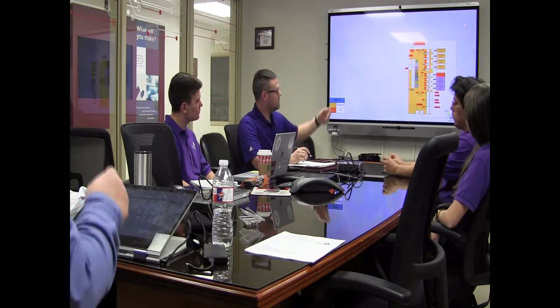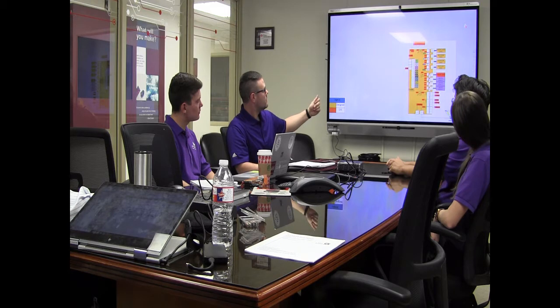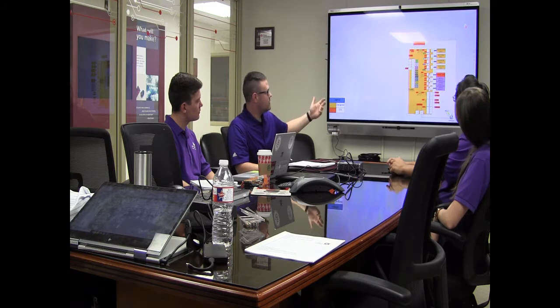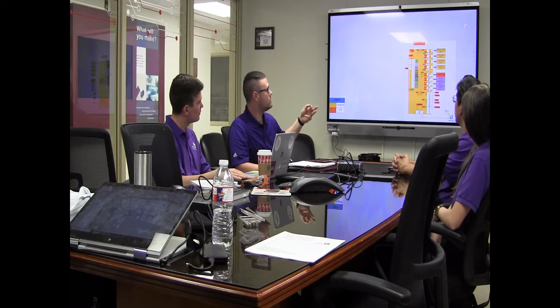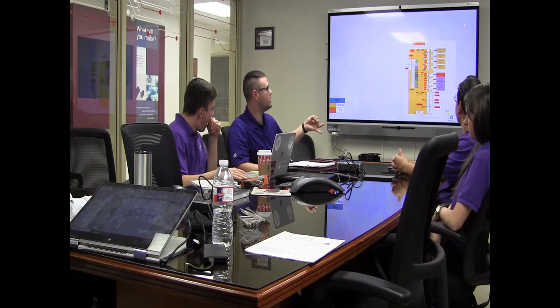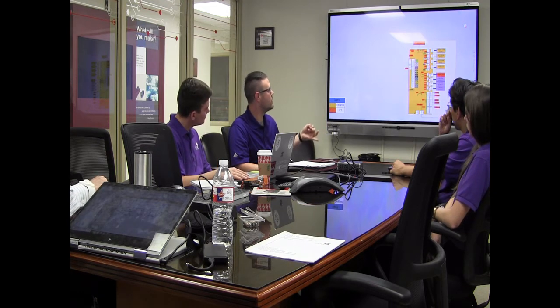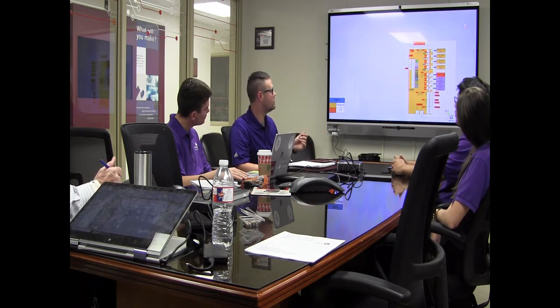and it's pretty straightforward to program. And then on the bottom 4, we have H bridges on each one, the 8870s, and so we have selectable voltage as well that we'll see in a second to each one of those. So 2 voltage lines, 2 grounds, and then 2 PWMs, either the low side switch PWMs or PWM through the H bridge. So it gives you lots of options that you can pull again.